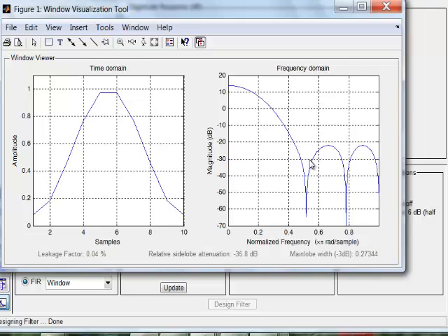As a result, we get a better quality for the filter in the frequency domain. The ratio between the main and the side lobes increases a lot, about 25 dB, and it's worth it for that. We know that these are the overlapping windows that should happen in the time domain. For the rectangular one, it considers everything with the same weight. As a result, we have a side lobe that is really high with respect to the main lobe, and that's how it's designed.